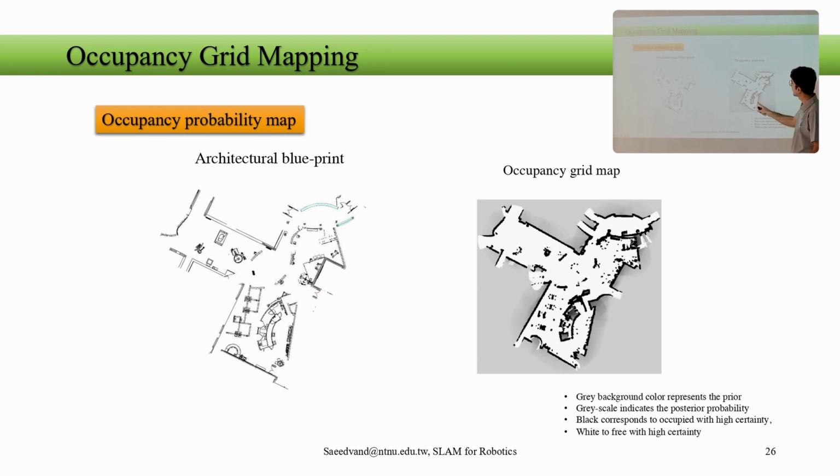For example, the black one is 1, the white one is 0, and everything is scaling between 0 and 1 in order to say how likely the obstacle is over there. So all those efforts were for what? Because we have the error on the observation and the localization, and when your robot is moving in the environment, we wanted to update the occupancy of one grid cell so that we couldn't put simply 0, 1.